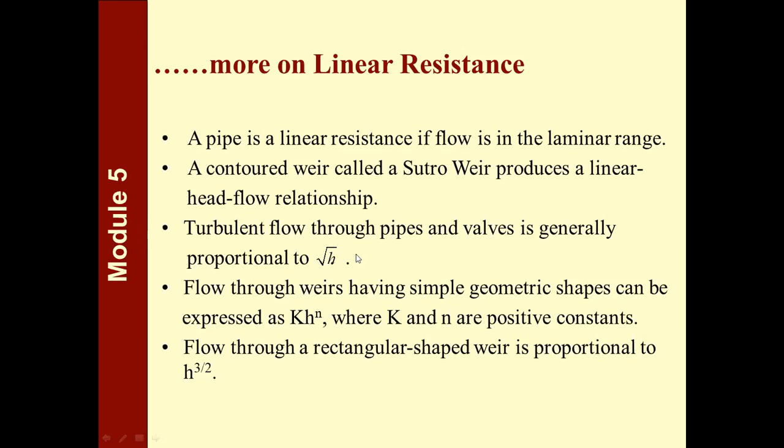So that's the time that we use what we call linearization. We substitute an approximate linear term for the nonlinear term in your model differential equation, which makes it possible for you to follow or monitor the changes in the level of the fluid inside the tank in terms of changes in the volumetric inflow. Remember that you are only allowed to use Laplace transformation for a model differential equation which is linear. If it's not linear, then you need to do linearization first, which is the last part of this set of slides.